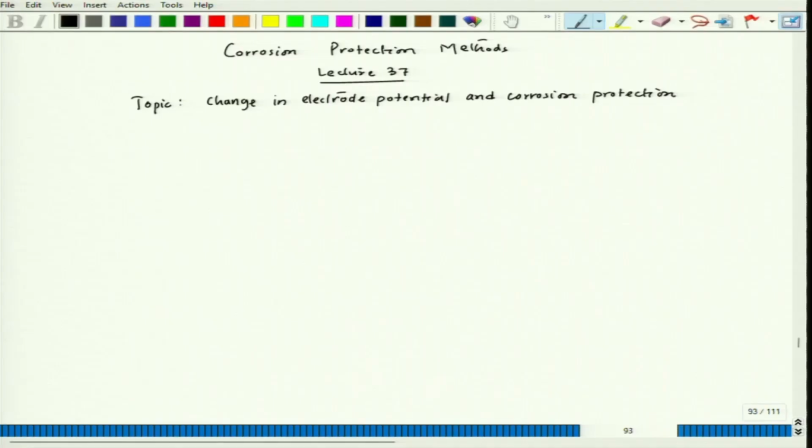In anodic polarization, initially it requires very high current density, but later on it goes to a very low current requirement to maintain the protection potential. And it's a direct measure of the corrosion rate we achieve during protection, whereas in cathodic protection, it's more of an empirical relation.